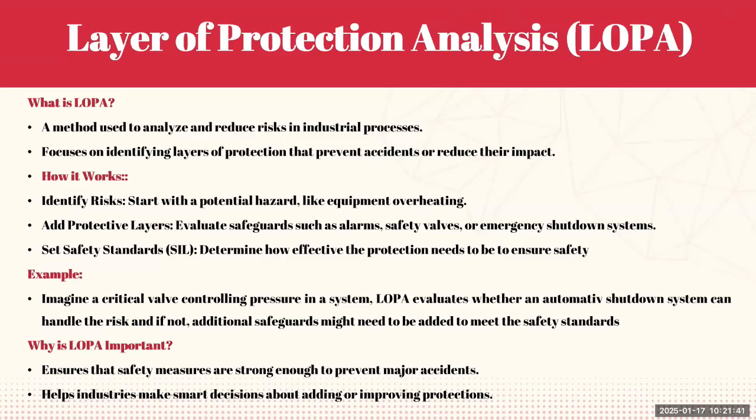So in short, LOPA is very important because it ensures that safety measures are strong enough to prevent major accidents and also helps industries make smarter decisions about adding or improving protections. So LOPA is like building a multi-layered defense system to minimize the chance of any single point of failure leading to an incident.